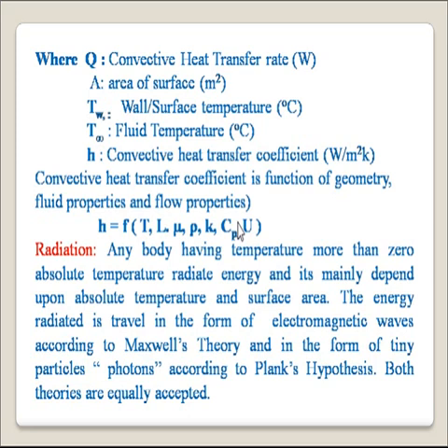Now we'll discuss the third mode of heat transfer, radiation. Any body having a temperature above absolute zero radiates energy, and it mainly depends upon absolute temperature and surface area. The energy radiated by a body travels in the form of electromagnetic waves according to Maxwell's theory.